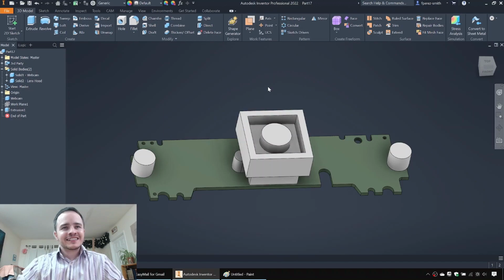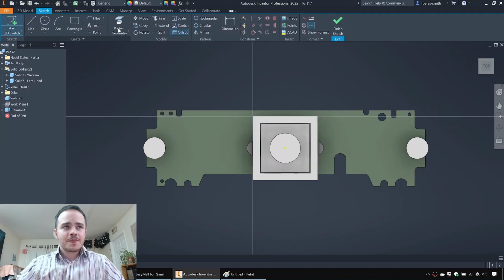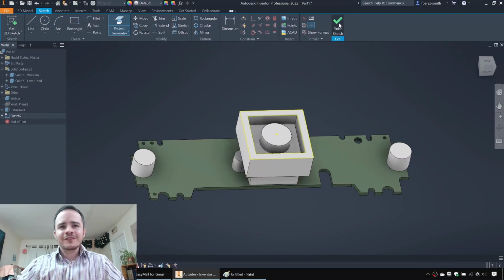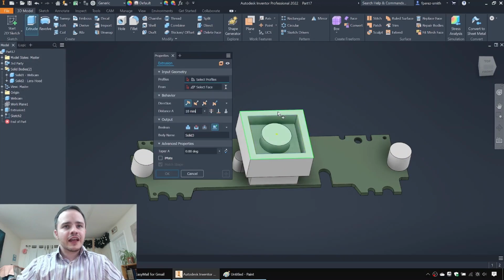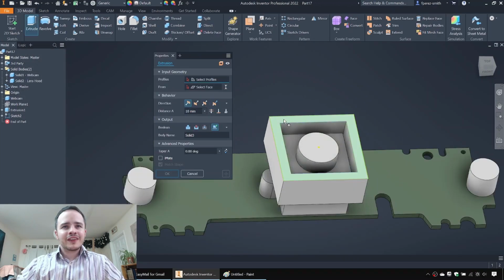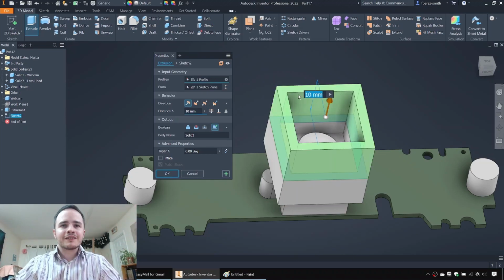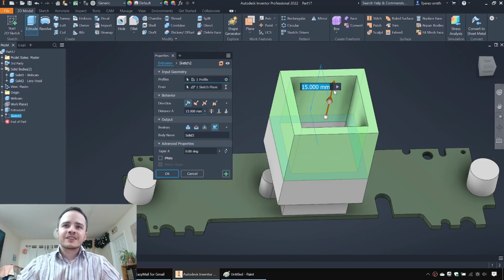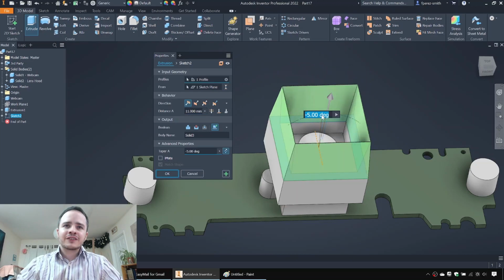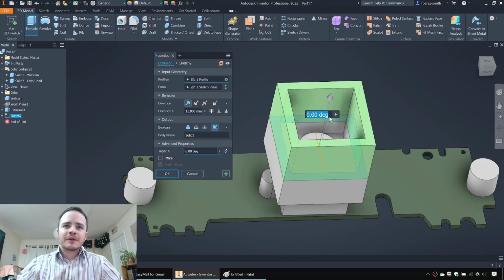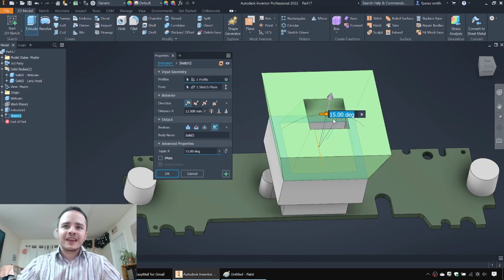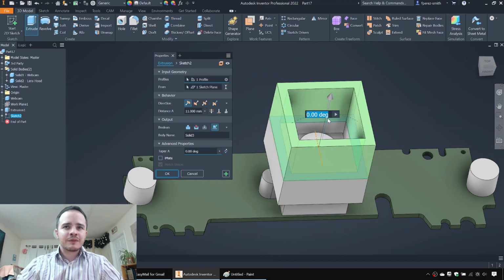We could have actually added just the distance to begin with, but let's just do it anyway. We'll say start 2D sketch, and we'll say project geometry, grab that profile, finish sketch, and extrude it again. Now, you might be tempted to say, okay, we can add in our lens flare here by adding in a taper. But unfortunately, when it comes to extruding out a second part, it might not do what you expect it to do. So the taper can make it sharp or it can make it fat on the end, but it won't make it flare out like we hope it to.